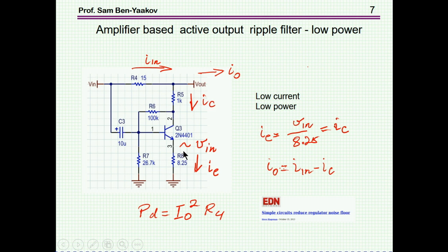So this is a shunt connection, and you absorb the current here rather than attenuate it as we've seen before. Now obviously there's another issue here of power dissipation. In this case it's depending on this resistor, which you must have in order to get an attenuation here. So this configuration is again for low power.